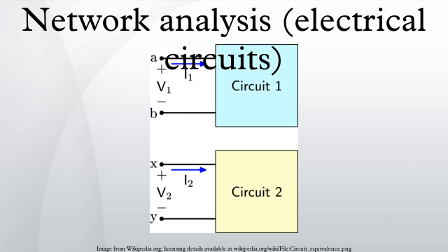Thus, the transfer function will be linear up to a particular point where there will be a discontinuity. Past this point the transfer function will again be linear but with a different slope. A well-known application of this method is the approximation of the transfer function of a p-n junction diode. The actual transfer function of an ideal diode has been given at the top of this section. However, this formula is rarely used in network analysis, a piecewise approximation being used instead.